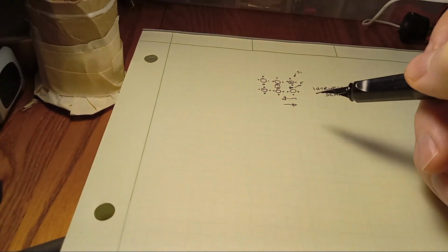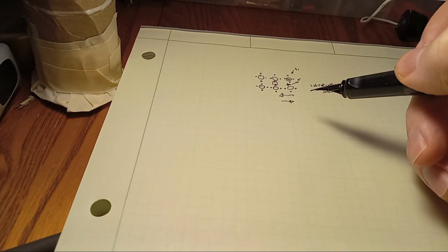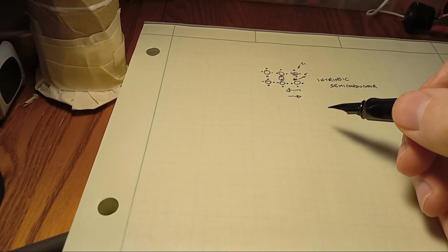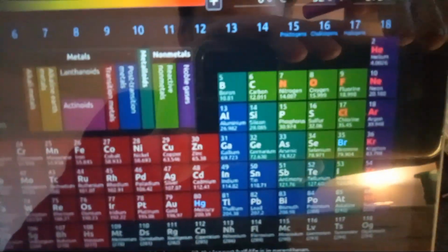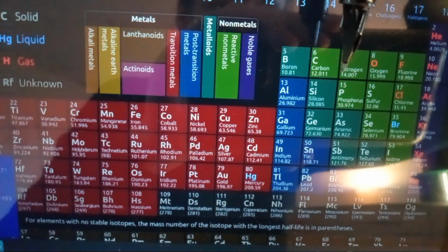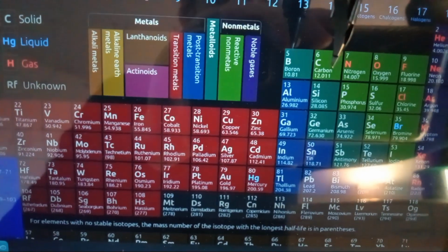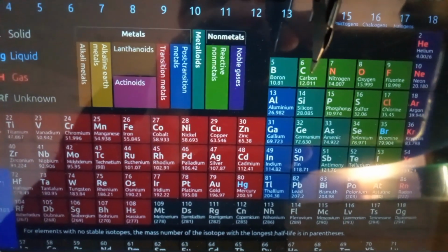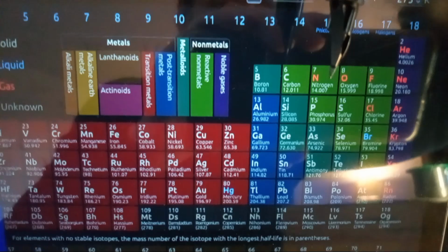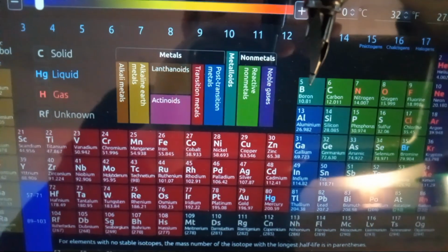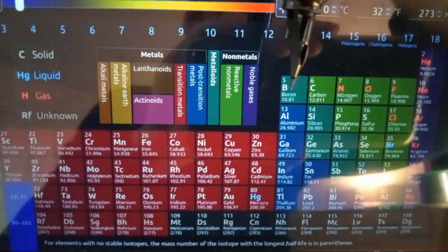However, you can make them conductive, and this is done by introducing small quantities of other atoms called dopants. Now, if you note the periodic table here, we're looking at the column that contains carbon, silicon, germanium. These atoms all have 4 electrons in their outer shell. Now, nitrogen, phosphorus, and arsenic all have 5, while boron, aluminum, and gallium all have 3.